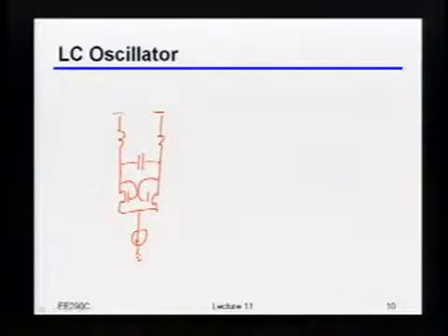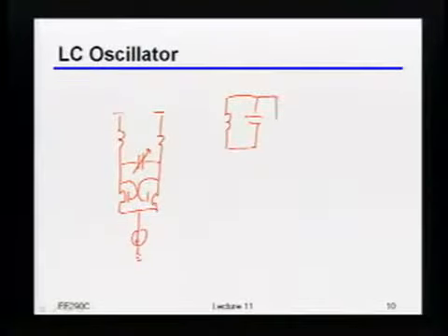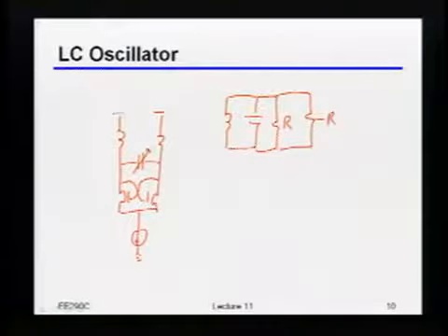But the idea here, and I'll add one important thing, is that because we are doing this inside of a PLL, you're going to have to tune something. Generally, you're going to tune the capacitance. The general idea in this kind of oscillator is that if you had some parallel RLC network, that R just represents the loss in the network. All you're really trying to do is put a negative resistance in parallel with that loss to make sure it's perfectly an oscillator, okay?